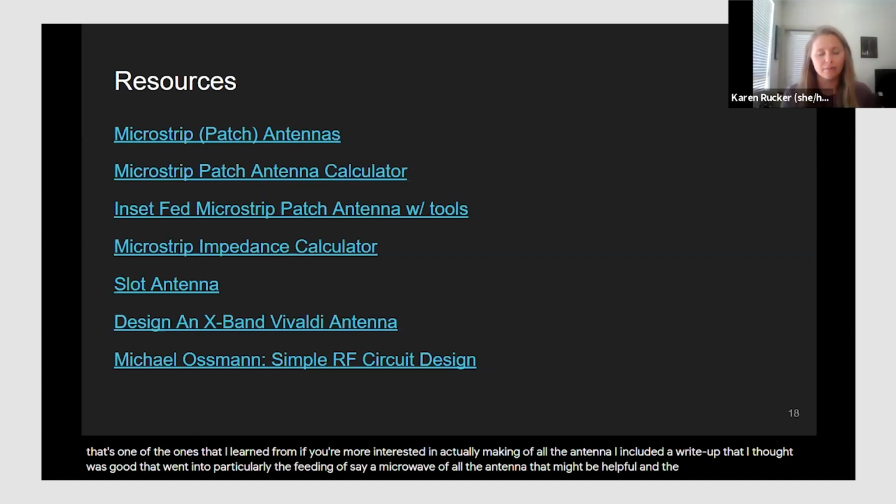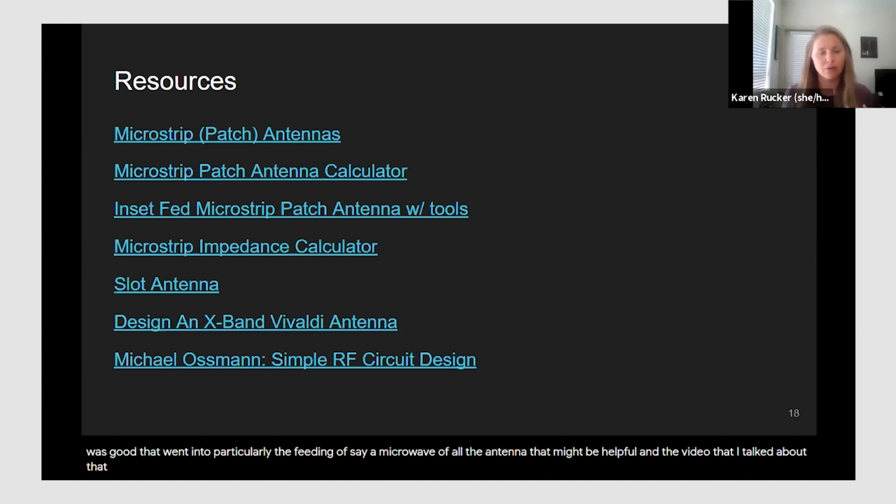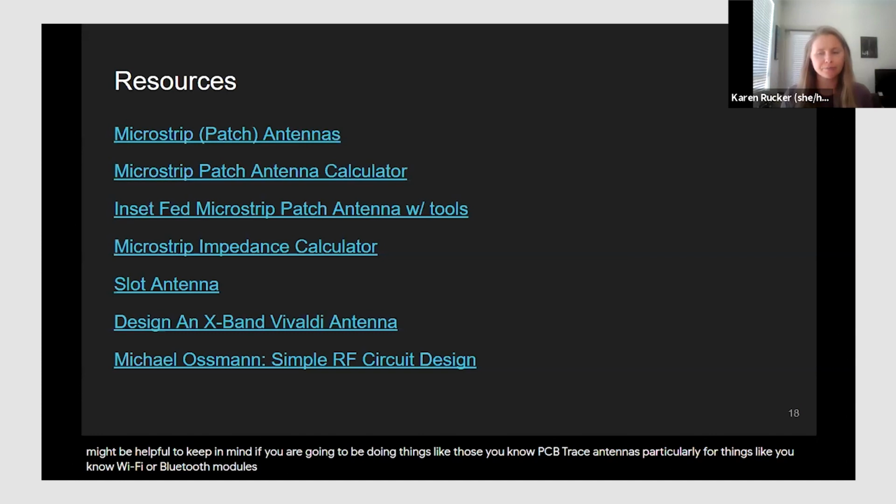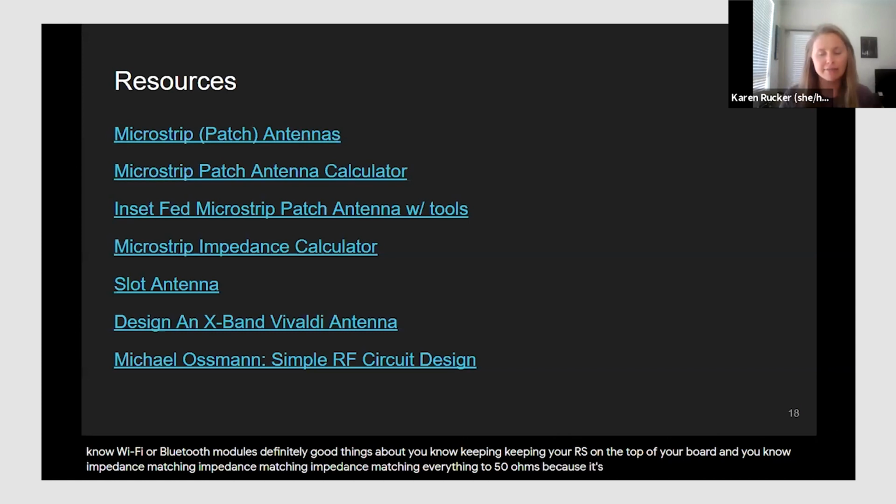And the video that I talked about that was helpful to me about RF circuit board design by Michael Osman. He goes over just some of the basics of what might be helpful to keep in mind if you are going to be doing things like PCB trace antennas, particularly for things like Wi-Fi or Bluetooth modules. Definitely good things about keeping your power separated from your RF traces, keeping your RF on the top of your board, and impedance matching everything to 50 ohms, because impedance matching is always rule number one in RF.